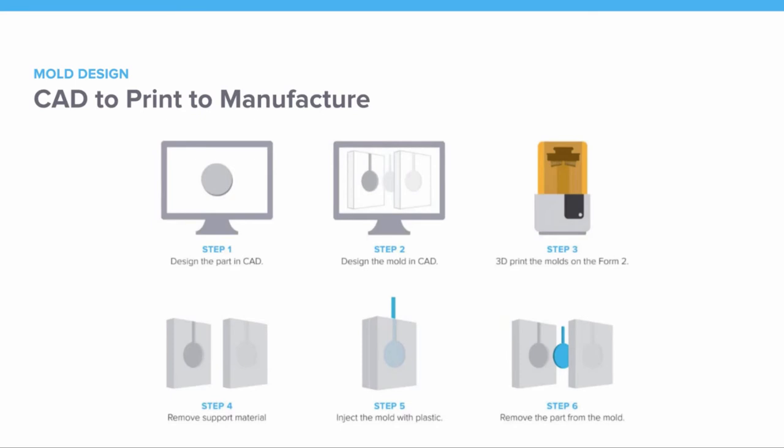So in terms of the overall process, these are the steps. Step one, design, print, put in the injection molding machine, inject, and you have your final part. If you'd like to use a standard aluminum frame, you can get those from an injection molding manufacturer. They're very common. You can have them custom machined by some other agencies. It's not super expensive. I think for maybe a 4x4 it might be under $300.